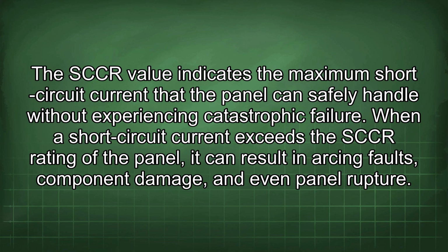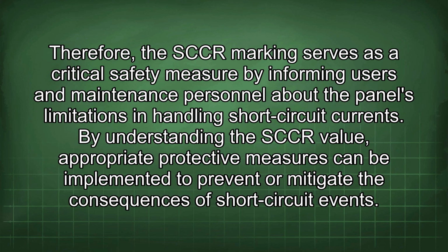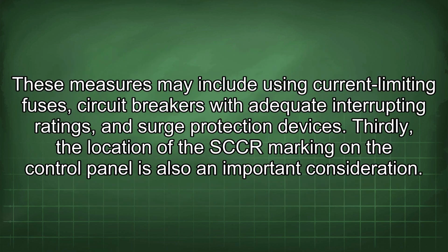When a short-circuit current exceeds the SCCR rating of the panel, it can result in arcing faults, component damage, and even panel rupture. Therefore, the SCCR marking serves as a critical safety measure by informing users and maintenance personnel about the panel's limitations in handling short-circuit currents. By understanding the SCCR value, appropriate protective measures can be implemented to prevent or mitigate the consequences of short-circuit events. These measures may include using current-limiting fuses, circuit breakers with adequate interrupting ratings, and surge protection devices.